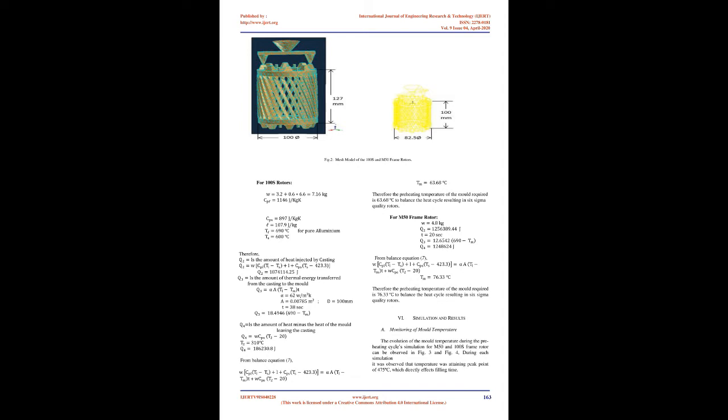3. Process parameters. The hydraulic die casting process is governed by its process parameters, so it is required to study its process parameters and their effects. Mostly casting defects are concerned with process parameters. Hence one has to control the process parameters to achieve zero defect parts. The metal flow in the die castings is influenced by the pouring temperature, die temperature, and the thermal conductivity of the alloy. In a typical die casting machine, the molten metal is poured into the shot sleeve through a ladle after the die is closed. A movement of the plunger, or piston, forces the metal through the die, resulting in the movable part coinciding with the fixed part.